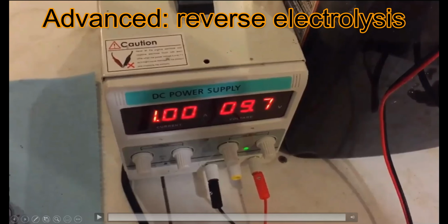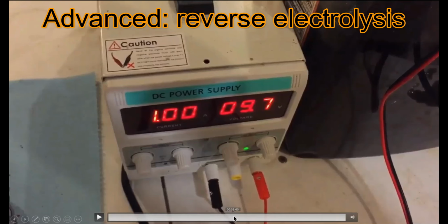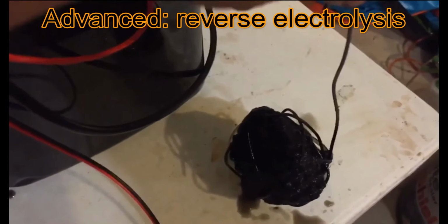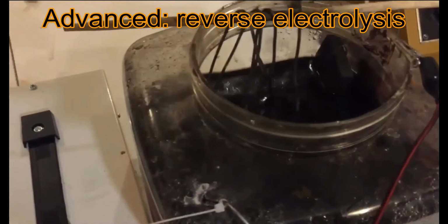You start putting things like stainless in there or copper, you're either going to get plating action going on or you're going to be releasing some fumes that you really don't want to be breathing. So you are off-gassing hydrogen too while you do this. So you do want to make sure you have good circulation and you're doing it in an area that's well ventilated. You're not going to build up gases there.